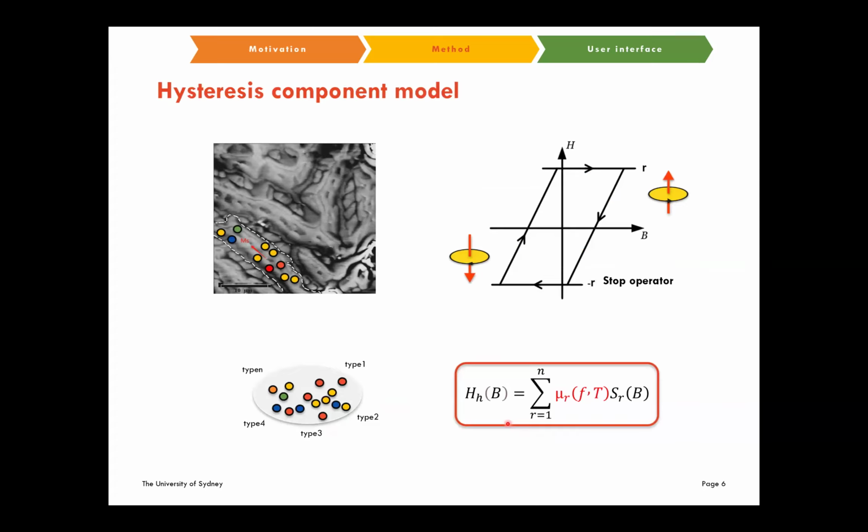Next, we are going to tell you how to model these two components. For the first component, hysteresis, in a classical physics-driven model, people tend to use operators, like the hysteresis operator, to model this effect. Hysteresis operator theory assumes there are infinitely many operators inside a material, and the average magnetization is the sum of all operators. The operator value represents the magnetization inside a tiny area.